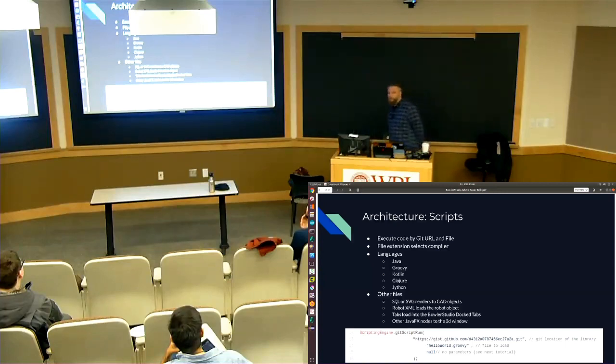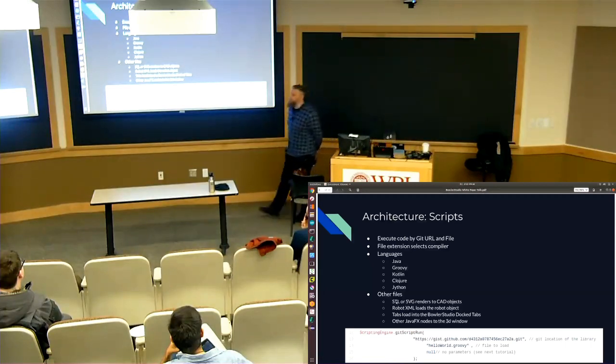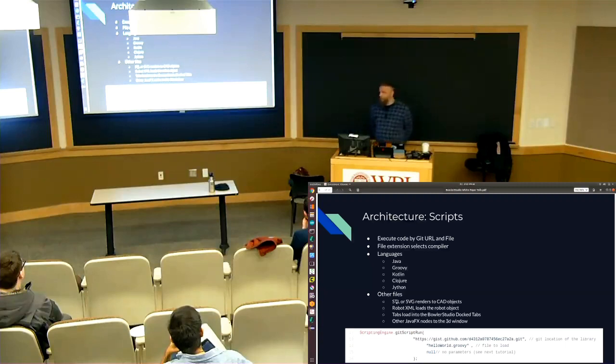Other files that it knows what to do with would be your STLs and SVGs. Those are generic interchange formats for CAD, 2D and 3D file formats, which are themselves generic formats. You can load an STL, you can export an STL. Once you load it, you can manipulate it, which is kind of cool. Same with SVGs. You can take a slice through any plane on the system and turn it into an SVG. It does not use sketch and extrude the way a traditional CAD package does. It actually doesn't do that at all. It uses constructive solid geometry, or CSG, as the standard modeling paradigm.